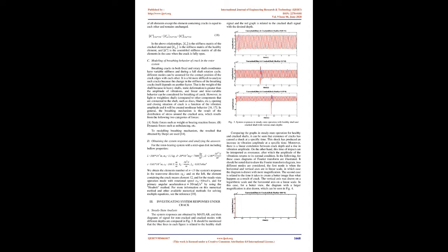It should be noted that the mass and stiffness matrices of the shaft element are symmetrical and the matrix of the gyroscopic effects of the shaft element is skew-symmetrical. The vector Q can include any type of force acting on the rotor system, whether external forces applied to the shaft, to the disc, or to the supports, or the forces caused by the unbalance. In this paper, only the disc unbalance force is considered.